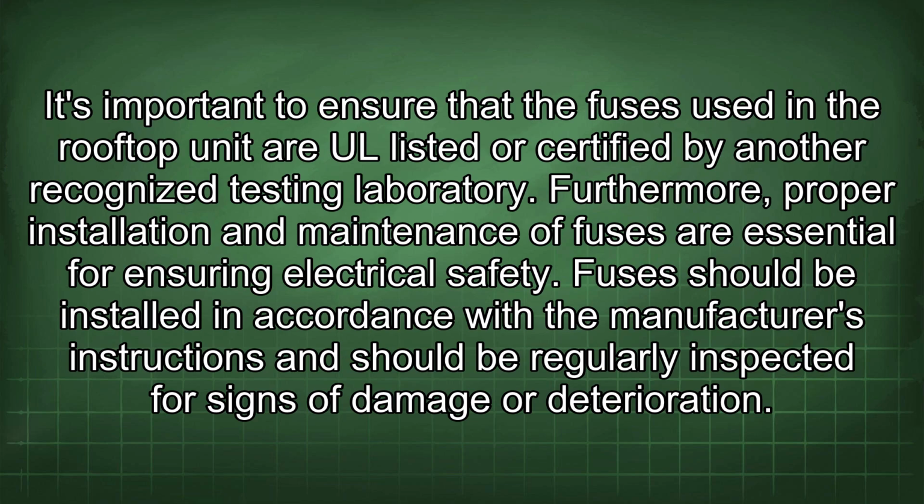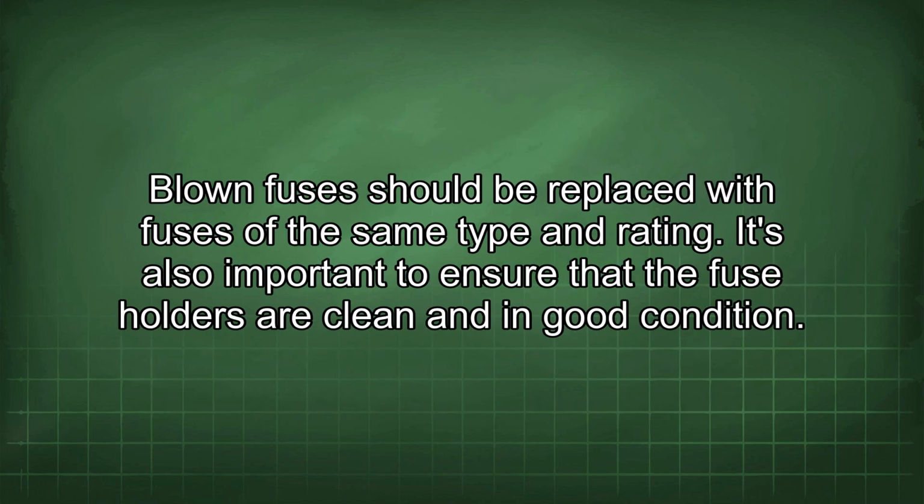Fuses should be installed in accordance with the manufacturer's instructions and should be regularly inspected for signs of damage or deterioration. Blown fuses should be replaced with fuses of the same type and rating. It's also important to ensure that the fuse holders are clean and in good condition.